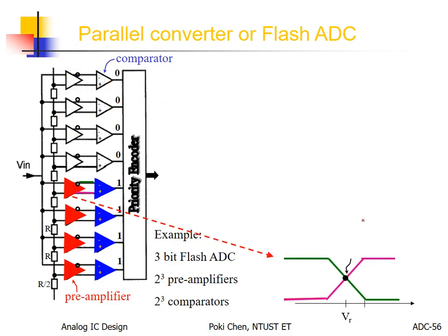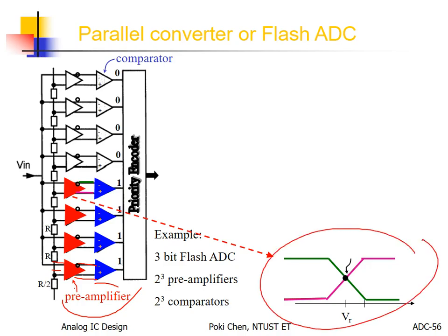And then, to explain the second reason for such a structure, we had better know that the preamplifier has two inputs and two outputs, so it is the so-called fully differential. For a fully differential one, the transfer characteristic curve needs to look like this.